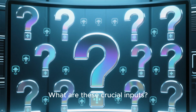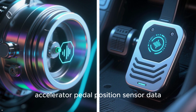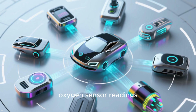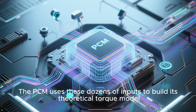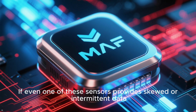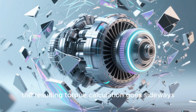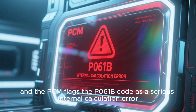What are these crucial inputs? We're talking about throttle position sensor data, accelerator pedal position sensor data, mass airflow sensor readings, oxygen sensor readings, and even transmission input speed data. The PCM uses these dozens of inputs to build its theoretical torque model. If even one of these sensors provides skewed or intermittent data, the resulting torque calculation goes sideways, and the PCM flags the P061B code as a serious internal calculation error.